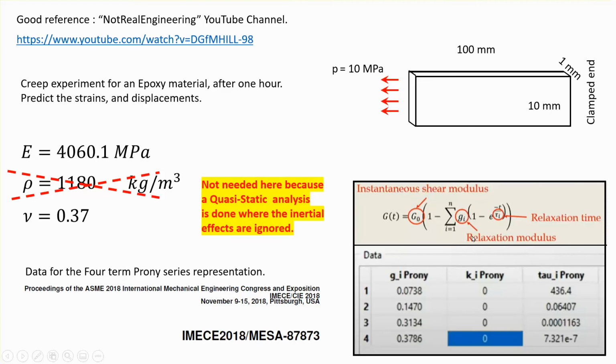Basically you need four sets of rows. Now the middle one, the K's, are not necessary in our problem. All we need are the g_i values and the tau_i values, and these tau_i are the relaxation times. So this is the data that's going to be inputted in 3D Experience.